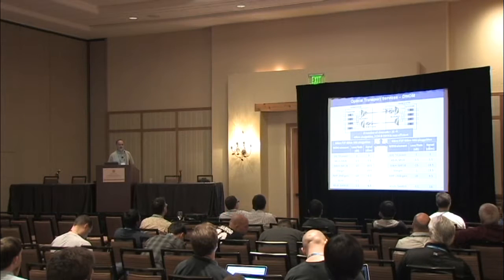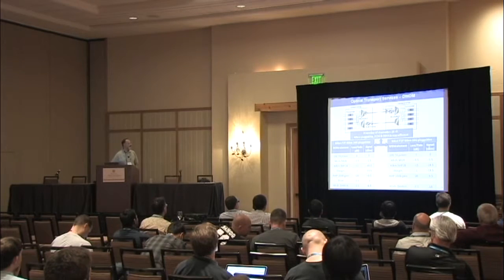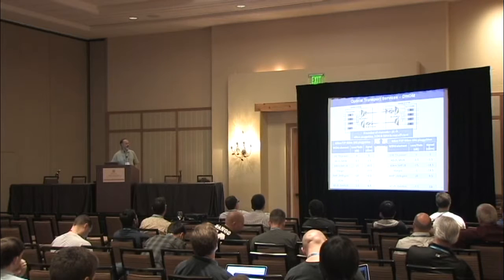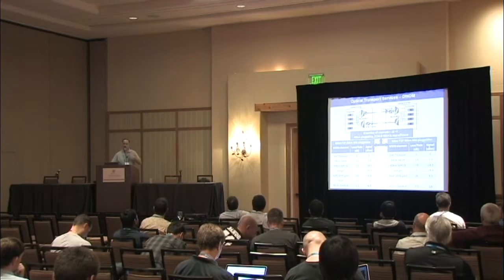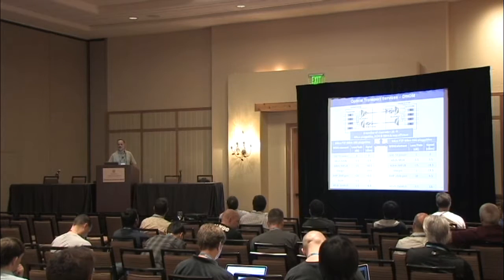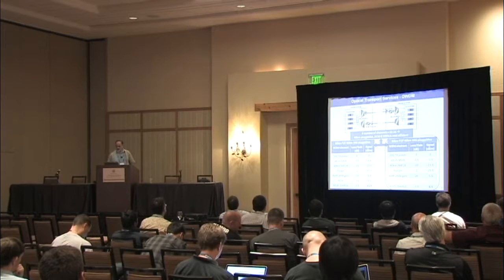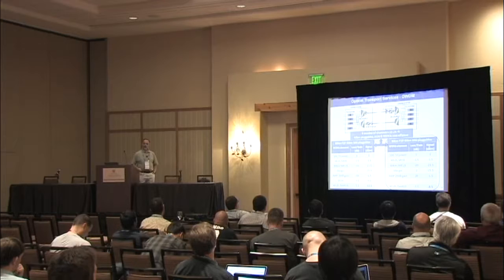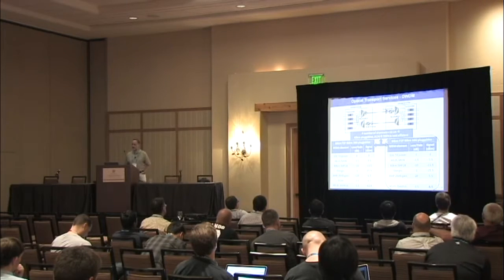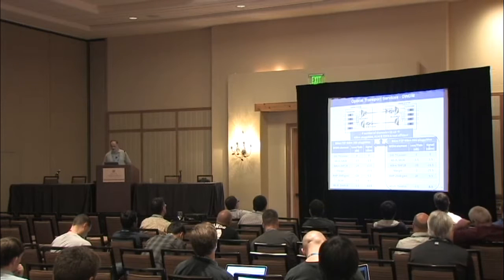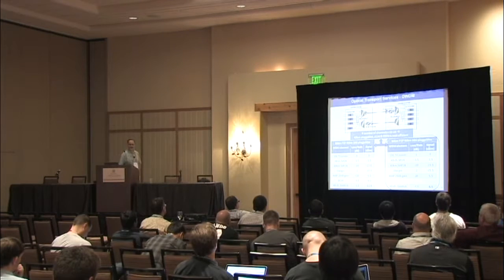Again, doing the economical calculation, an empirical number is somewhere around 16 channels and beyond. I'm better off economically using 40 kilometer optics and an EDFA and dispersion compensation. And I dare to do the same exercise for an 80 kilometer link. Even that I put it in red, for the 80 kilometer, I still prefer to use the 80 kilometer optics, but theoretically this is doable.